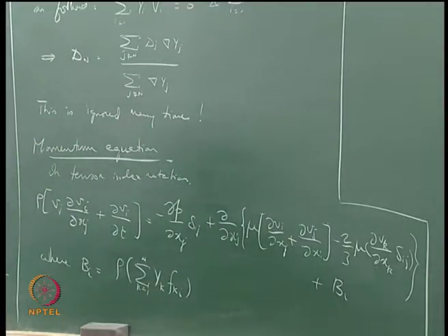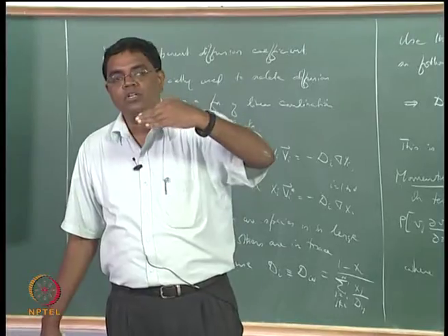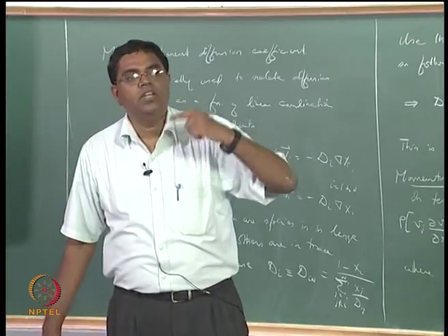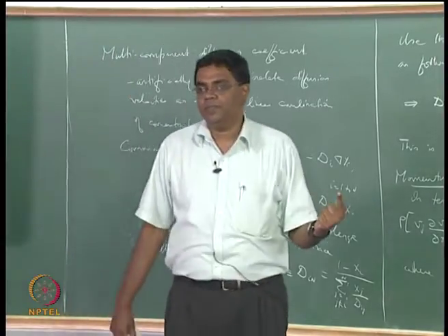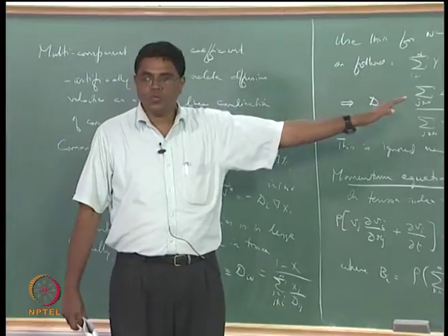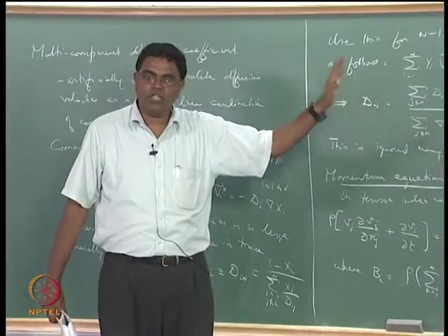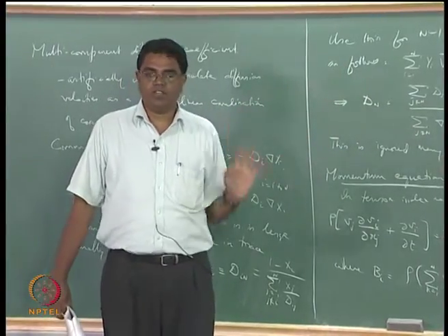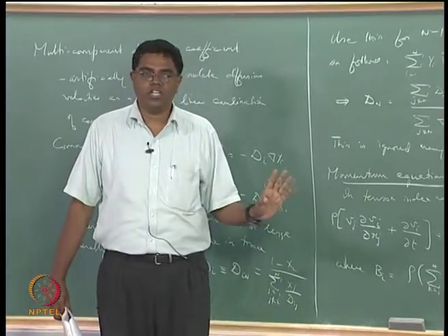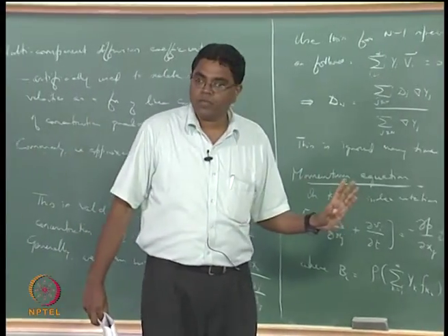So if you now obtained your mechanical energy and subtracted it from the energy equation written in terms of the stagnation enthalpy, then you get an energy equation that takes into account only the thermal energy conservation. That is what we would do. We would just write out the equation for the thermal energy conservation. We will not worry about the stagnation enthalpy at all.